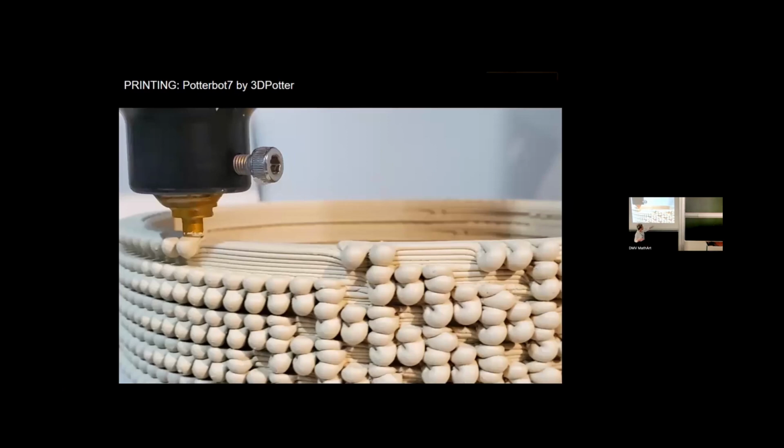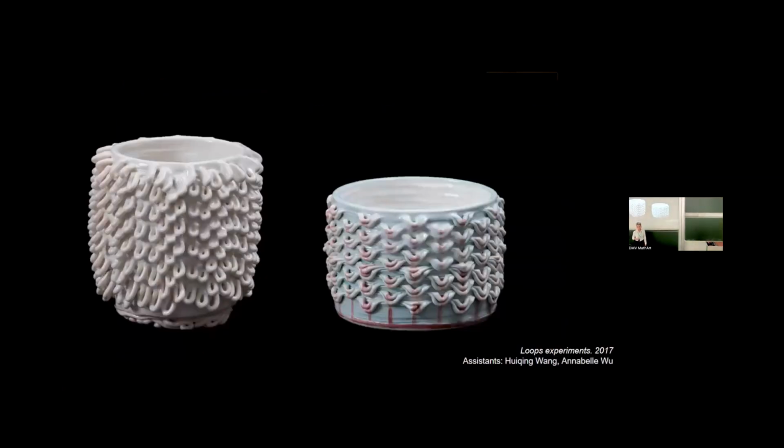I wanted to recall this image of the printing so you can see it up close. If you have smaller volumes stuck onto a larger volume, and those smaller volumes are unsupported, there's usually this juicy kind of droop loop that is created. I discovered that by accident. It really was just the wall collapsing on one side, and then the next layer would detour out to whatever it was supposed to be, and then drop down. And that's how I noticed, oh my gosh, I can get loops.